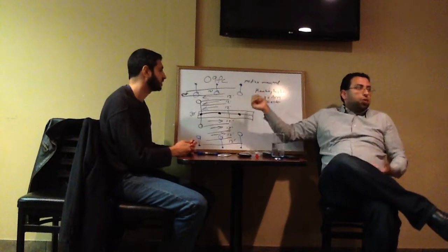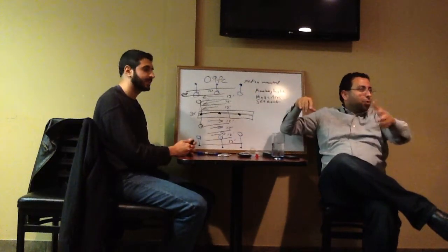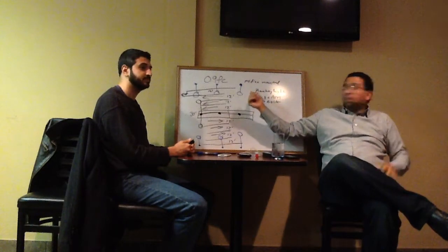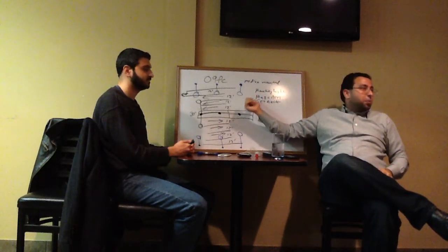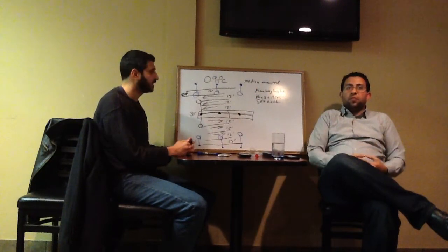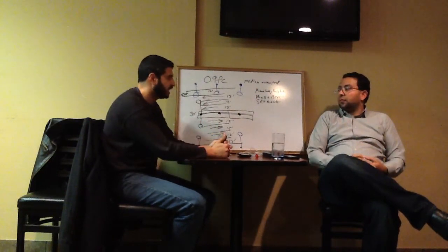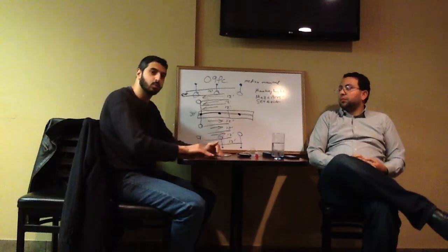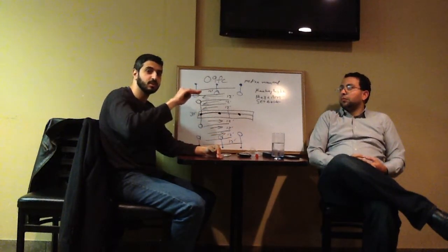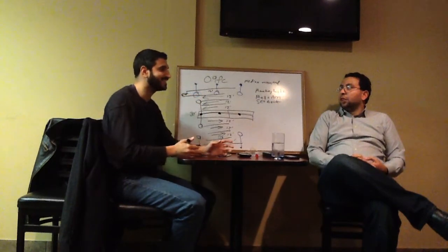Do you guys have any questions? Even if we record, go ahead and ask. Mounting height is clear. Mast arm, setback, everything's clear. Can you go over the mounting height one more time? Again, it's not the actual height of the pole, but the height of the luminaire, the bottom of the luminaire.